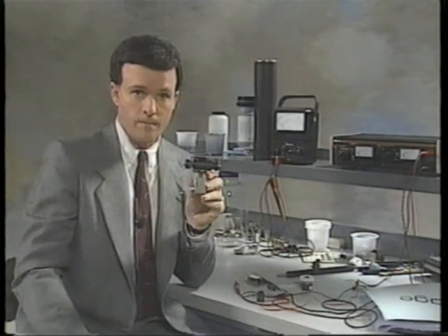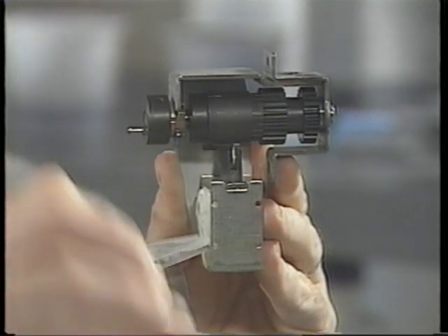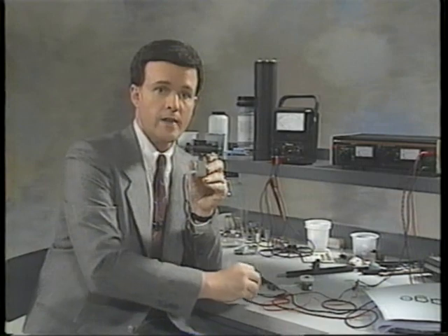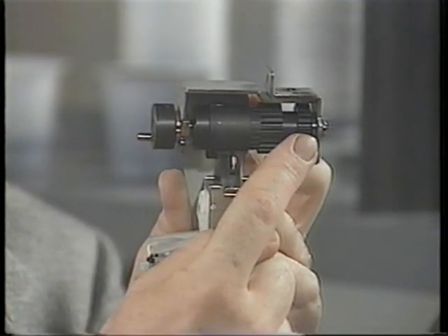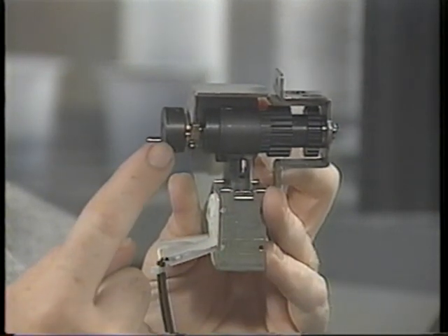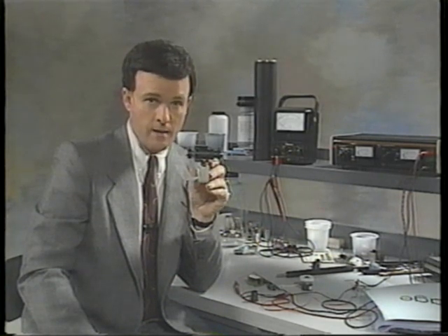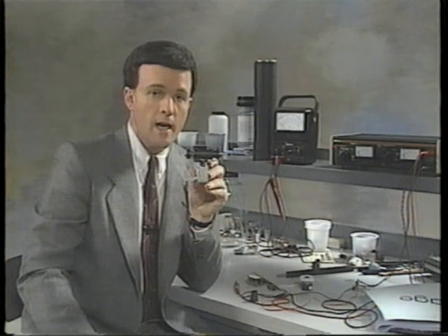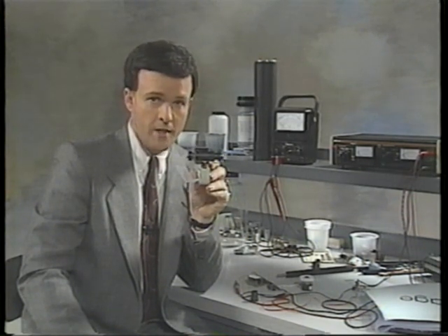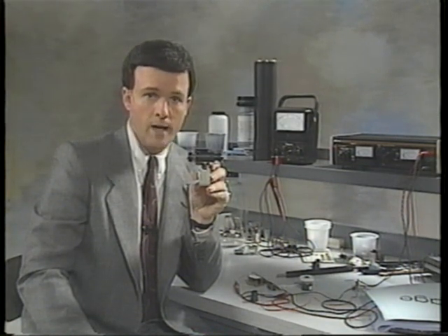This is a spring clutch. It's basically a tightly coiled spring surrounded by this sleeve. Inside the spring are two drive pieces. One supplies rotation from the copier's motor, while the other transmits that drive to a roller. Under normal circumstances, the spring grips both pieces very tightly, so both sides of the clutch turn as one unit. To release the clutch, an actuator forces one side of the spring to expand. It moves away from the drive piece inside, so motor drive is removed and the roller stops turning.